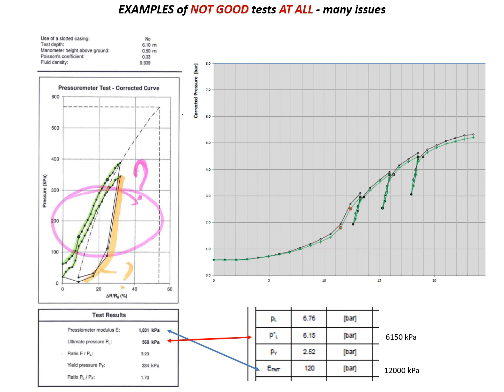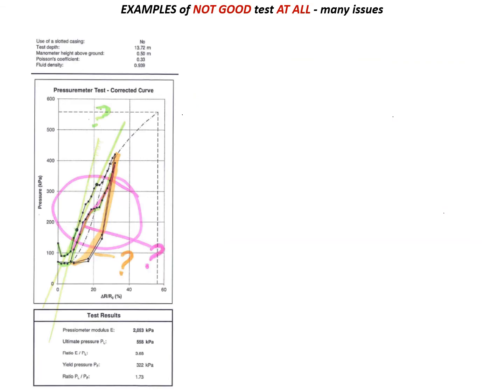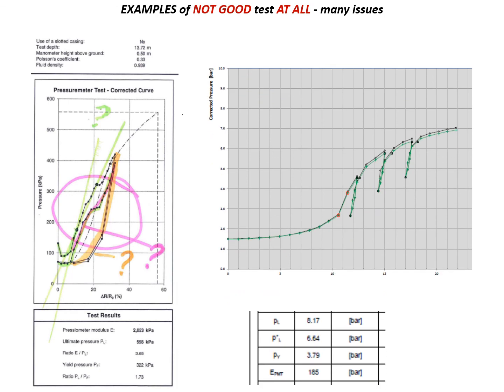So what I would like to tell you guys, if you see such a bad test, don't trust it. Even it doesn't matter what is written in the table, it doesn't make any sense. So you have this 10 times difference between a good test and a bad test. The same site, the same depth, the same borehole, like first test, first trial, another borehole, and again 10 times. So if you see a not good shape, the test is not good. Doesn't matter what test you're going to do: gradation, Atterberg limits, triaxial, consolidation, pressuremeter, point load test, not like a test on rock samples. Doesn't matter. If the shape is not close to classic, I mean, don't speak about several points, don't take these results into account.